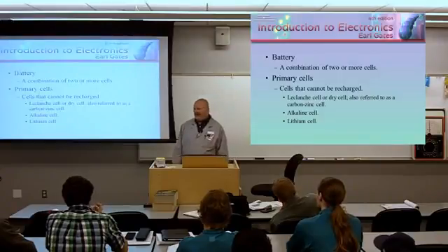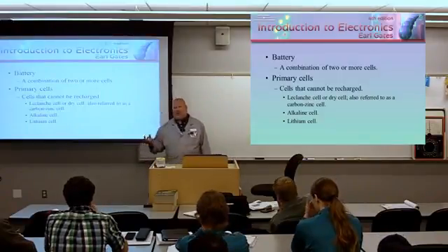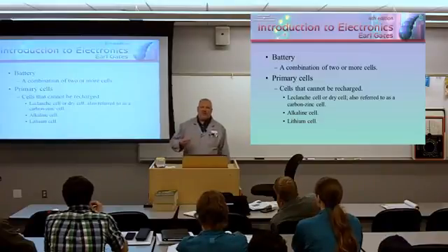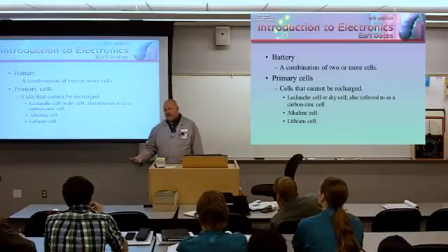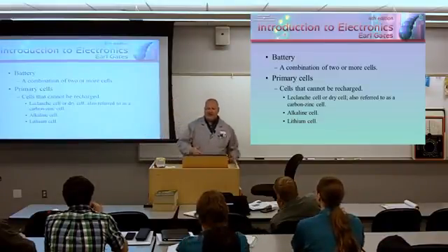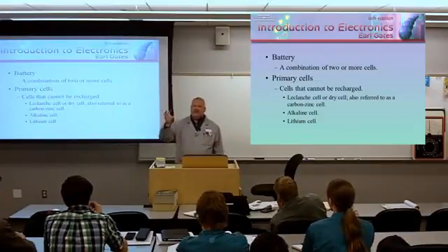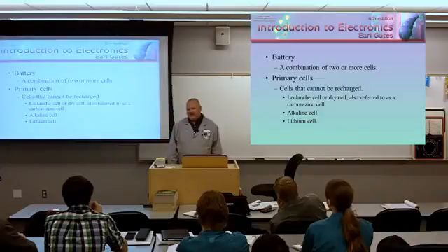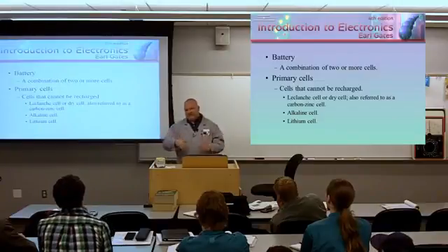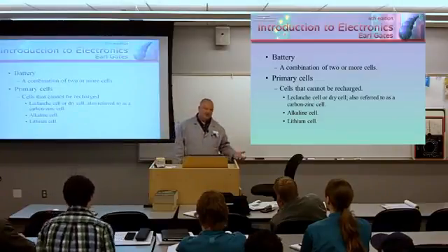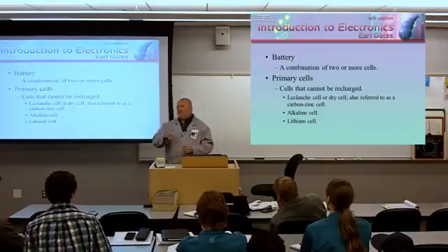On my airplane, there's something called an ELT, Emergency Locator Transmitter. In the event of a crash, a G switch triggers a transmitter to start sending out a beacon that gives your position away to search aircraft. Actually, they used to have satellites that looked for that signal, but now, long story, they've switched those satellites off. They've gone to some different frequencies now, but it would transmit.